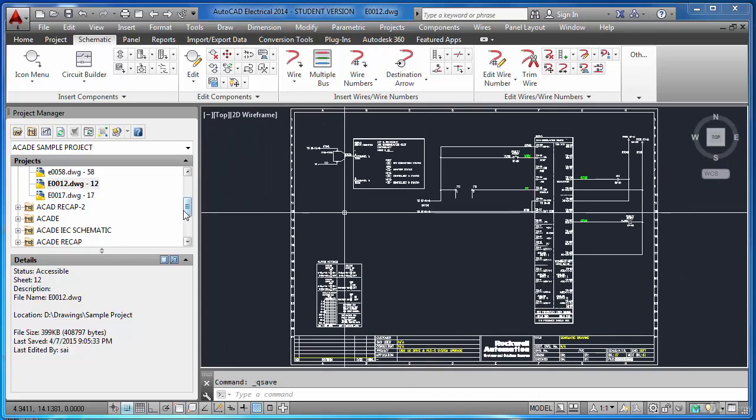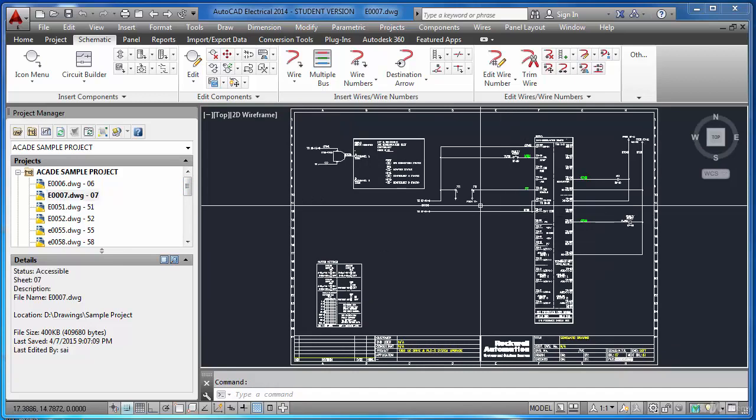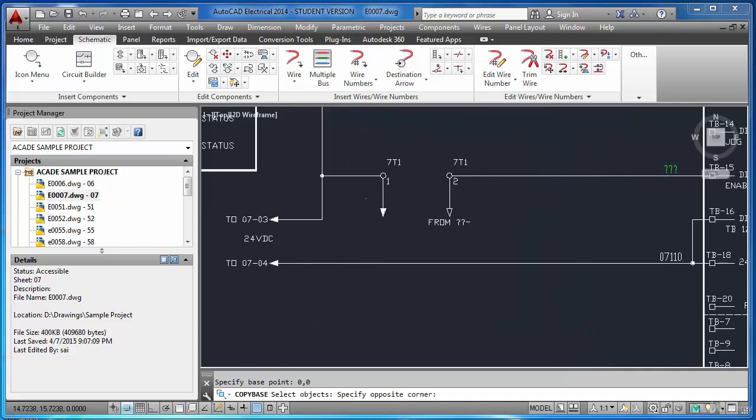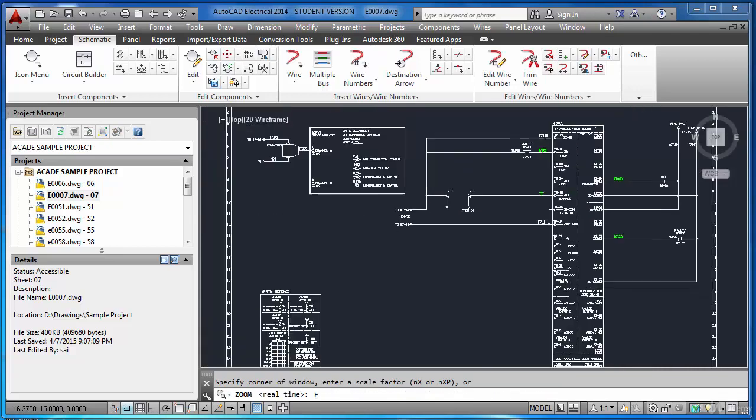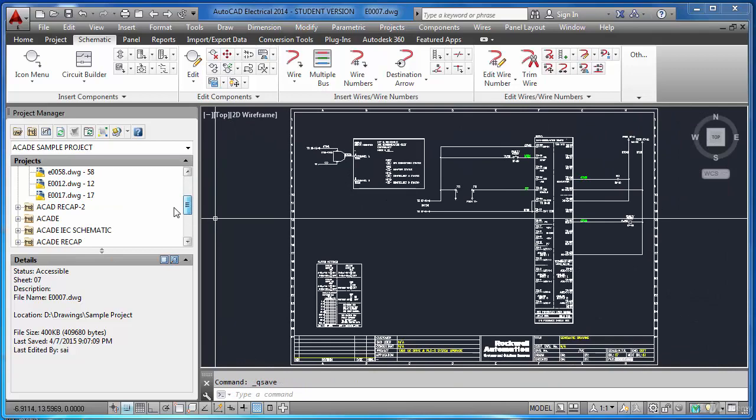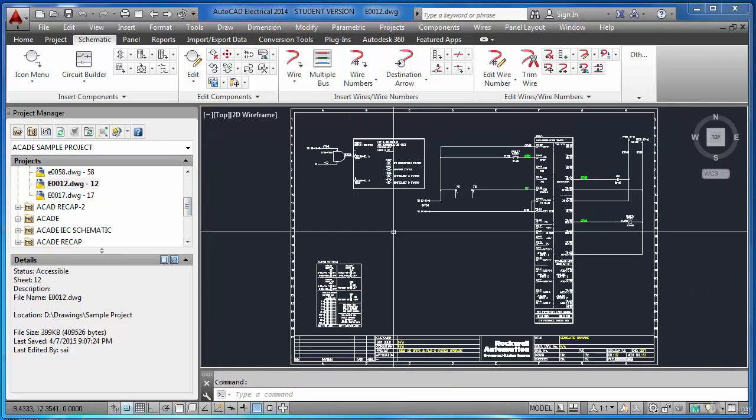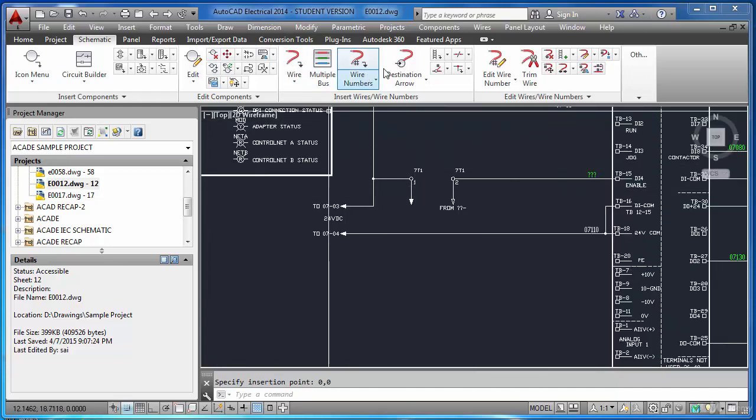So what you should ideally do is, all these drawings are on the same position 0 0. We have not moved any of these drawings. If you are sure, then you can apply this way. Just Control Shift C, base point 0 comma 0, select objects, just copy these two. Go to that sheet, Control V, 0 comma 0, it is here. Now you just have to edit.